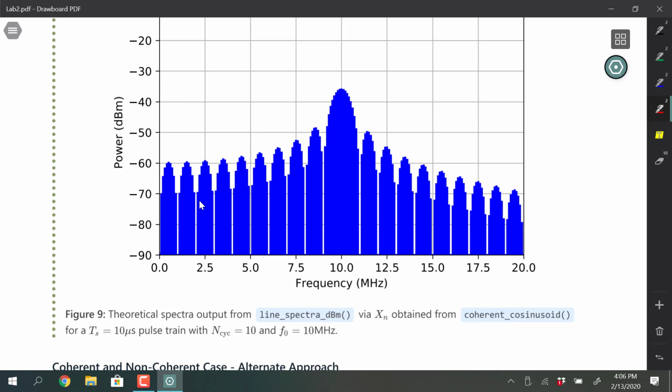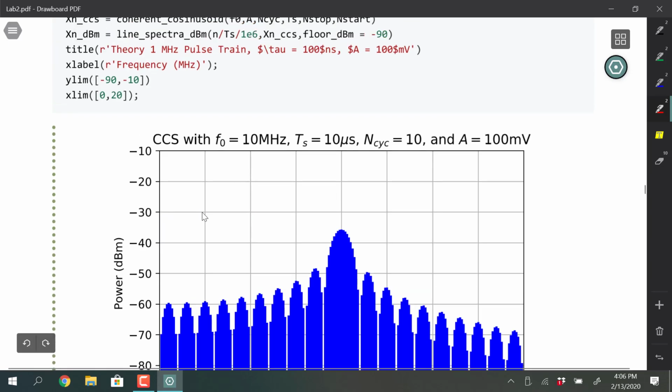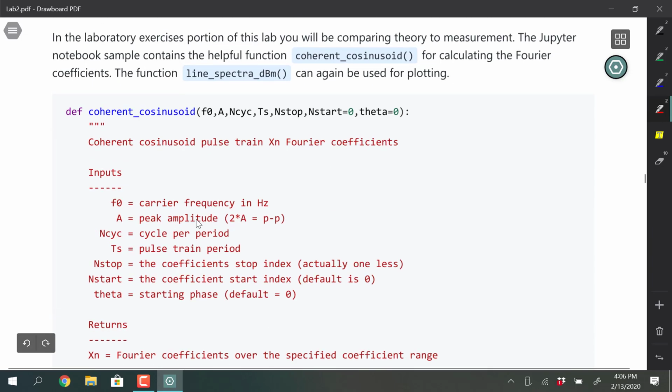But what's going on is when you move it up onto a carrier, in this case, the spectrum that's lapping down towards DC, there's that mirror image in the negative frequency, and that's lapping up through. So the two are actually crisscrossing, symmetrical on a double-sided spectrum. Yeah, because you've got these two blobs and the tails on the inside cross over each other. If you move the carrier frequency out further, then that tends to disappear.